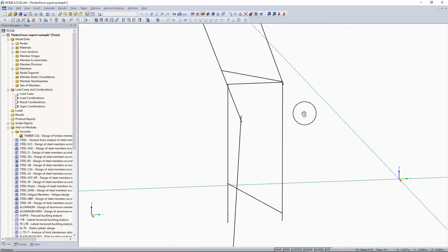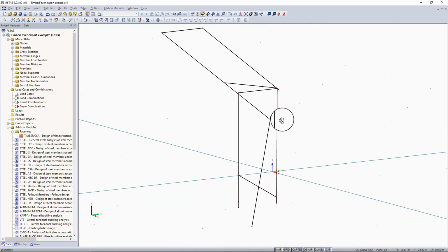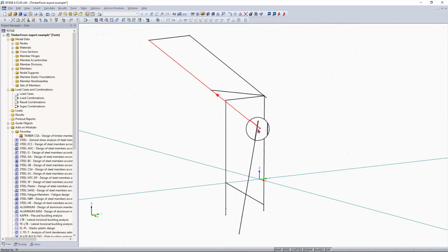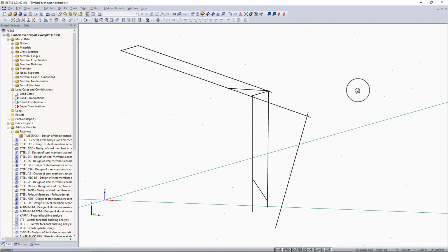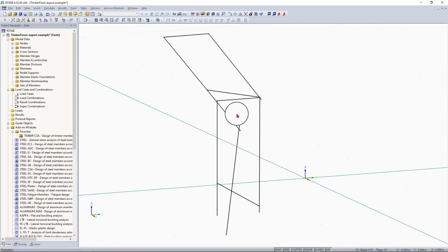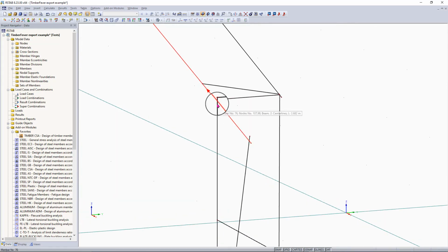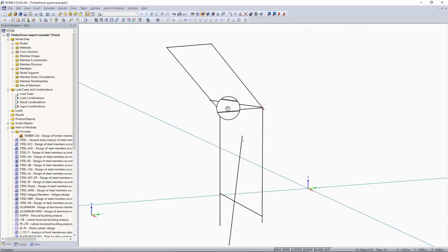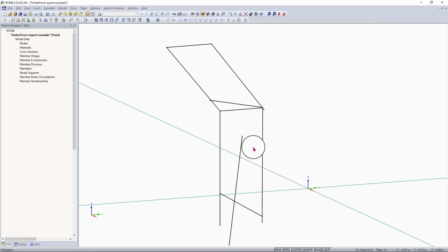So now you'll see that we're just left with this simple frame here. And what we want to do is make sure that we get everything squared off and aligned correctly. So what we can do first is take this line, left click and drag it to start at this corner node here. Then we can delete this other node right here.